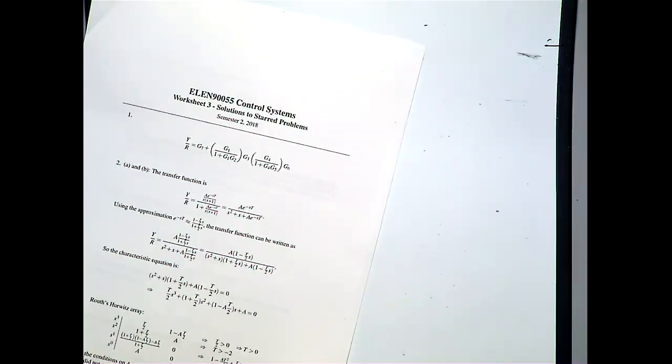Now you are looking at a transfer function of what happens to Y, how this R is mapped to Y, how this W is mapped to Y. That's what a transfer function does. A normal transfer function, if you have a system, you have an input, you have an output, will give you an output equal to, let's say this is G of S times U of S, right?